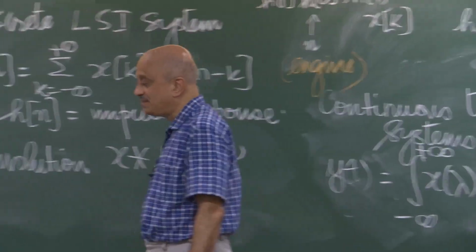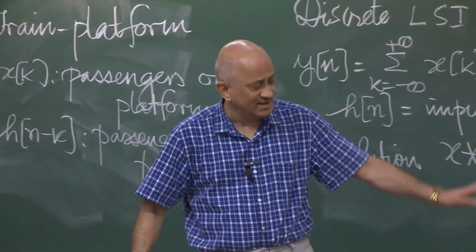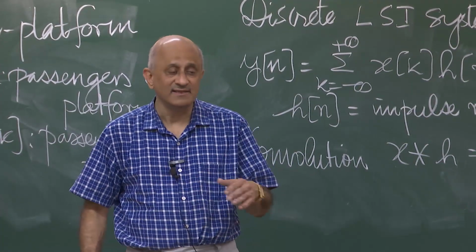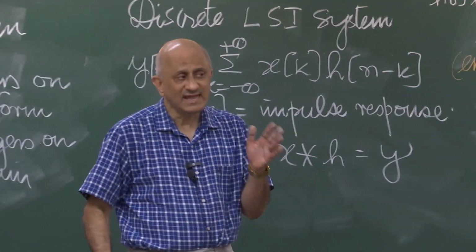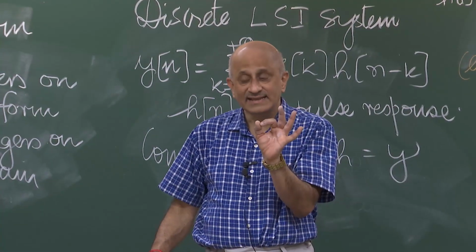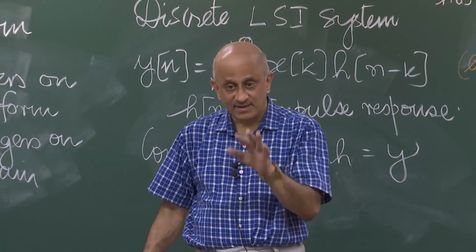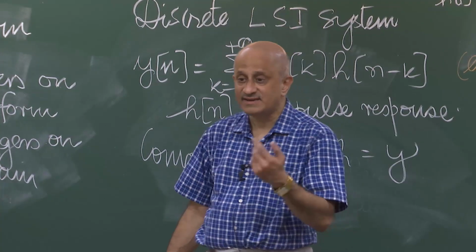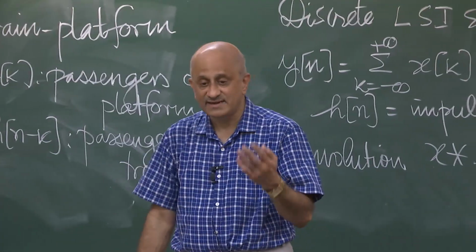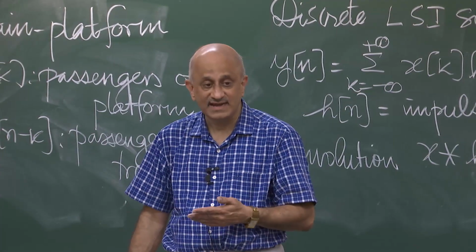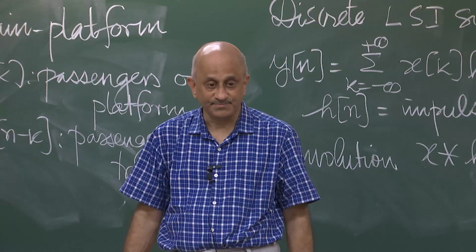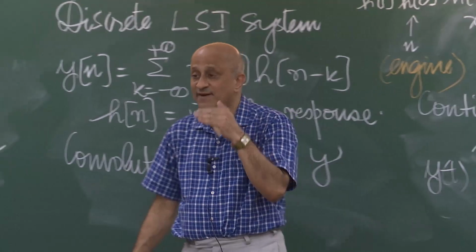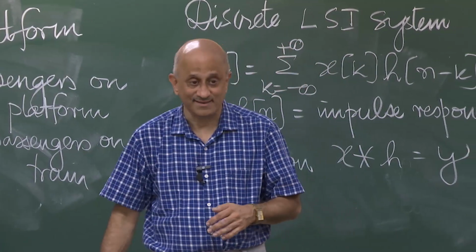Now, of course, the proof of this can be done in a manner similar to the discrete case, by essentially seeing what happens to one impulse and then expressing an input in terms of the impulse function, and then using the properties as we saw yesterday, shift invariance followed by additivity and homogeneity followed by additivity, to establish the input output relationship. Anyway, the point is that this operation of convolution is fundamental to dealing with linear shift invariant systems.